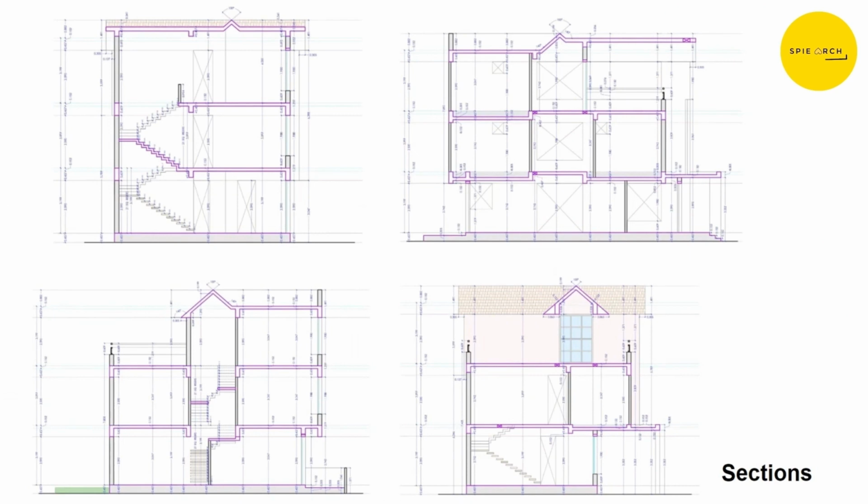The section on top right shows the sunken slabs at the skirts from the toilet areas, that is 2 toilets on the first floor and 1 on the second floor. Then the section on the top left shows the section cut from the staircase area. In the section shown in the bottom left corner, we can observe that some part of the staircase goes into the bedroom on the ground floor. So this part of the bedroom having low height is used for placing a wardrobe. Next.